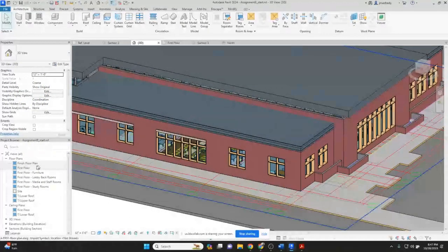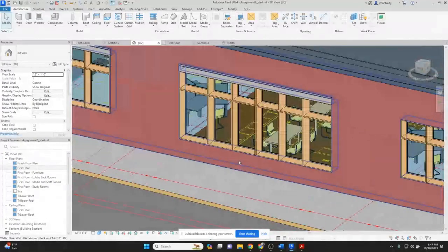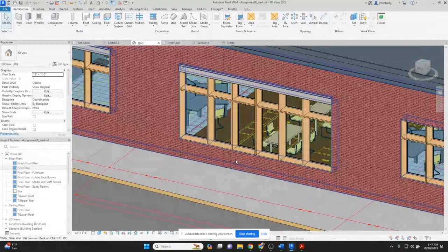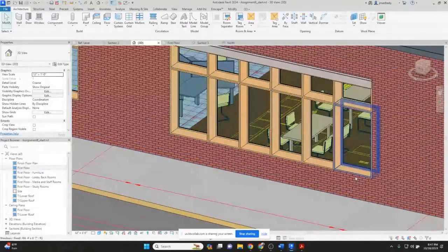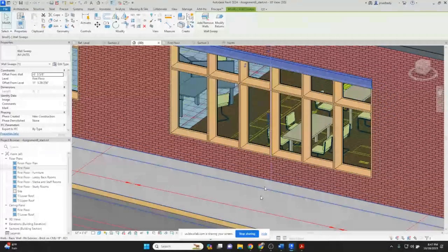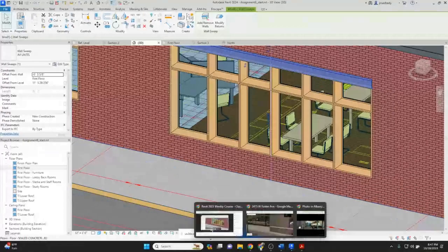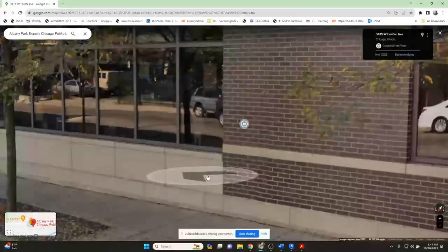So if I wanted to build this out here, depending on if you want the sill or not, you can build that entire object here as a profile, a custom profile that you build into the wall at the thickness shown here. Or you can build a sill, and this piece down here below is a split face.